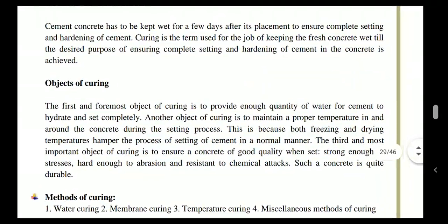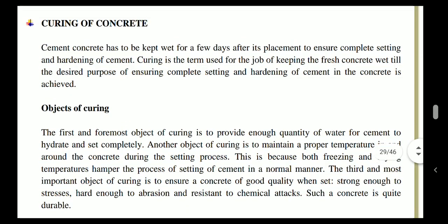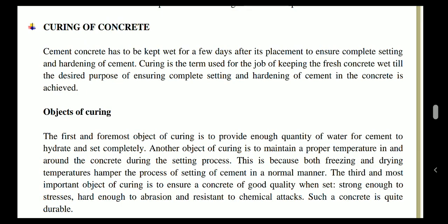Then another most important property of concrete is curing of concrete. Cement concrete has to be kept wet for a few days after its placement to ensure complete setting and hardening of cement. So curing is the term used for the job of keeping the fresh concrete wet till the desired purpose of ensuring complete setting and hardening of cement in the concrete is achieved.